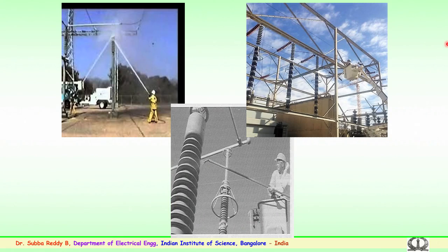Some of the energized conditions give some methods which are followed, such as hand pressure jets, which are used for cleaning during live line conditions. The distance of the personnel and the equipment being used is also very important, and how the cleaning procedure has to be done with the help of an insulating trolley, where personnel use an insulating mechanism for cleaning the insulators. This is again a similar method for cleaning substation insulators with insulated equipment.